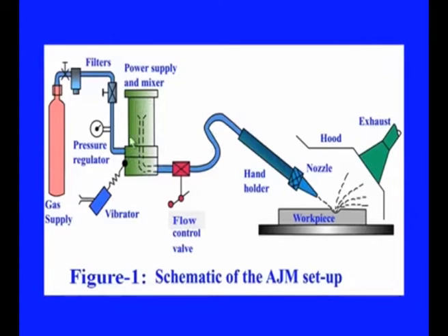Moreover, to get proper mixing of this gas and the abrasive particles, these are vibrated at some frequency, and therefore, the problem becomes magnified. Therefore, the life of this particular component is generally very less, and this causes the increase in the cost of operating in this particular setup.